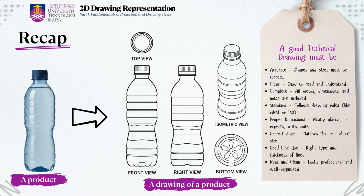Now, what makes these drawings good? On the right-hand tag, we have summarized the key criteria. A good technical drawing must be accurate, shapes and sizes must match the real product. It must also be clear and easy to understand, especially for someone who didn't create the drawing. It should be complete, meaning all the necessary views, dimensions, and notes are present. It must follow established standards, like ANSI or ISO, so that there is consistency across the industry. Dimensioning is also critical. The numbers and units need to be properly placed and easy to read, with no duplication. And when it comes to scale, the drawing should reflect the actual size or a proportionally accurate version of it.